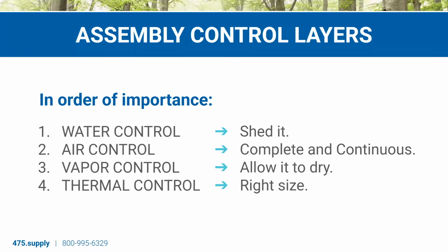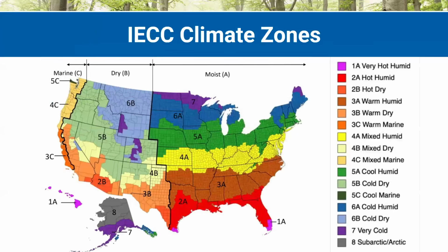And then for R value, it'll be the right amount based on your climate. You can refer to energy code for your region for what to be hitting for that. Or you could be basing it on like a PHIUS prescriptive standard or things like that, or ultimately maybe running a WUFI hydrothermal analysis on it. So appropriate size for your R value. So again, this is all coming back to which climate zone you're in and how we're kind of adjusting things.